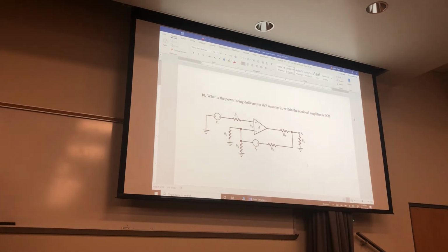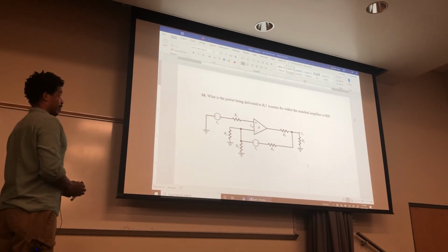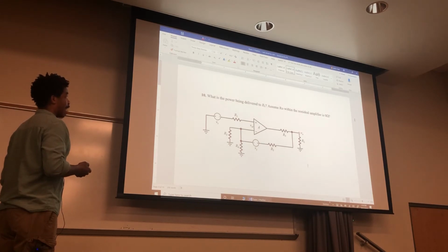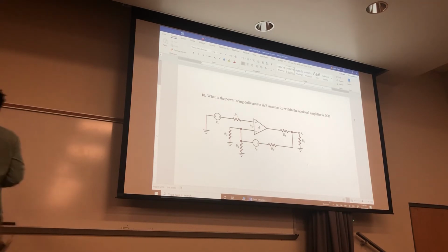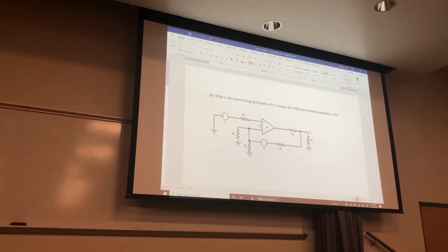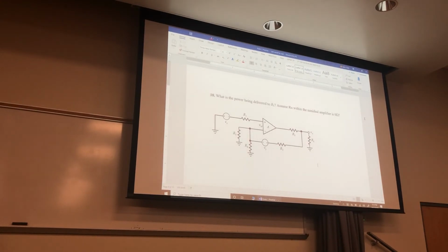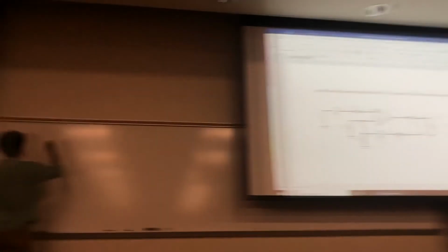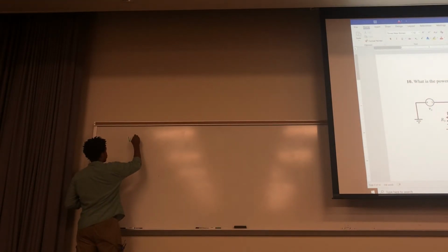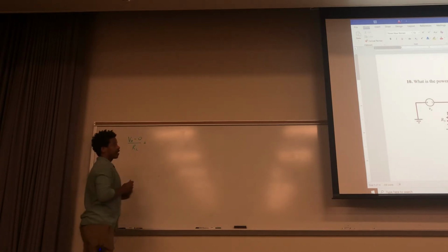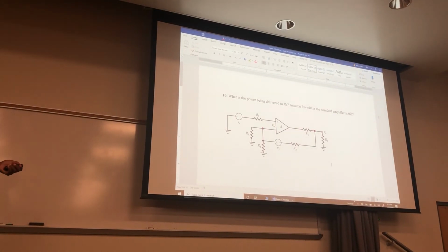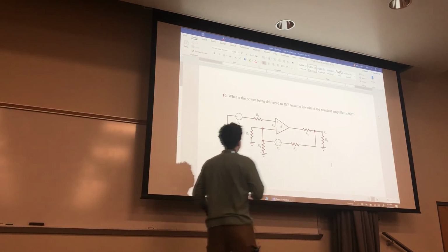Okay, so basically this is a problem of just trying to find out what this Vout is, right? So we could just do KCL right there. First let's do the easiest one, the current going down this direction. That's going to be Vout minus 0 over RL. Now the current going this direction, okay, so that's VID.